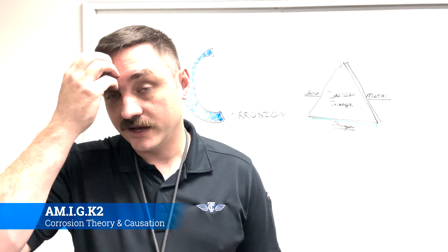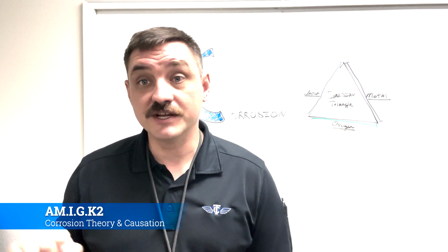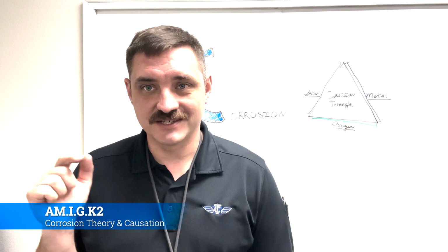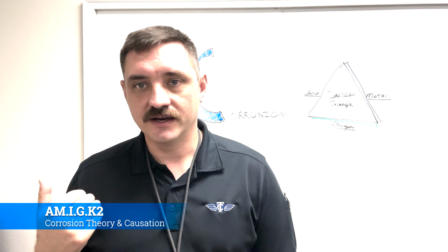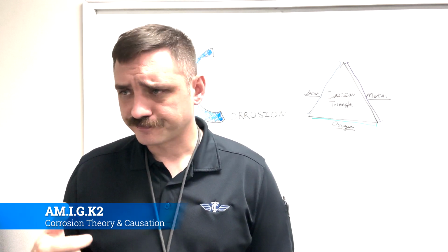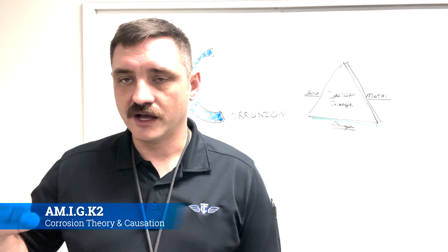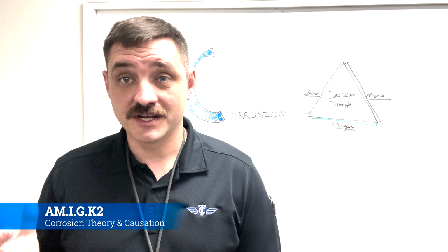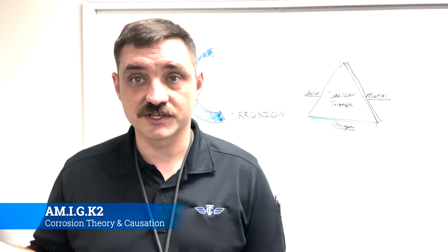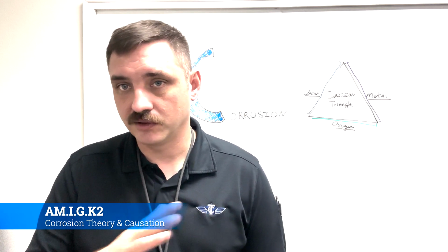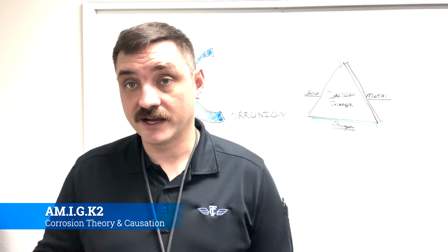This is why, if you end up flying over salt water, you'll end up doing engine washes on a regular basis, because as the engine flies around, it's soaking up all of that salty air, and that's getting on the blades inside the turbine, and you need to do a freshwater rinse to get it out. So you'll shoot it up with some soap that is basically a corrosion inhibitor that goes over the blades, and you'll dry run the motor, just let it suck it all up until it starts coming out. Then you'll do a freshwater rinse to blow all that soap out. That way, it helps inhibit that corrosion.